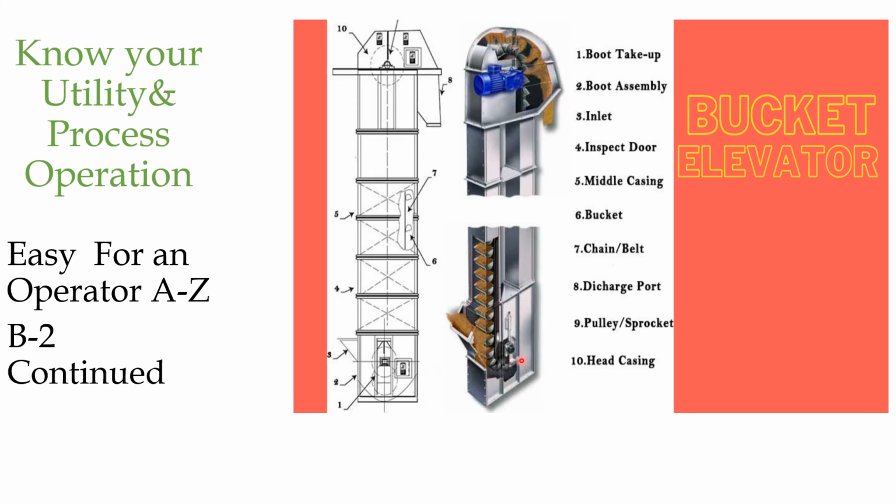What you have to do is frequent cleaning in the bottom boot, because the material spillage you cannot avoid, even though it is a closed or tightly sealed casing. Small spillage will be there due to the gap given between the casing and the bucket to avoid rubbing. So periodically you have to clean the boot to avoid damage or frequent maintenance in the bucket elevator. Hope you might understand some of the important terminology starting with B.